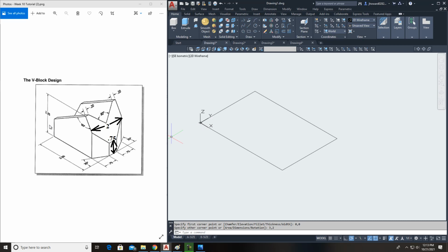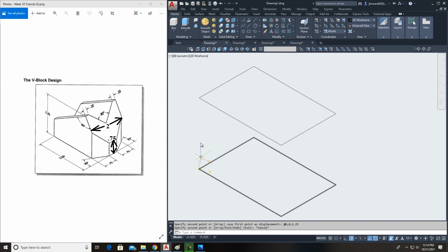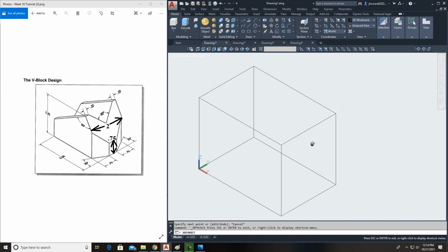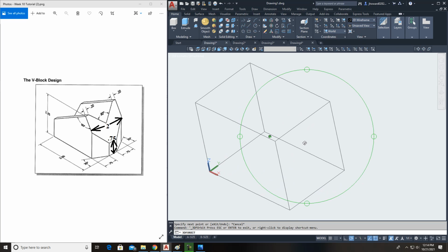And again, I want to go ahead and make my 3D portion of it. I'll add my depth, and I'll just do a copy, right click, center point, and I want to go at 0, 0, X and Y 0, and then comma 2.25. And again, you notice I hit at. I didn't have to, that was 0, 0, but it's just a habit I have whenever I'm doing those types of things. Bring that in there just like that. And I always like to do a little orbit just to make sure everything looks good. Looks great to me.